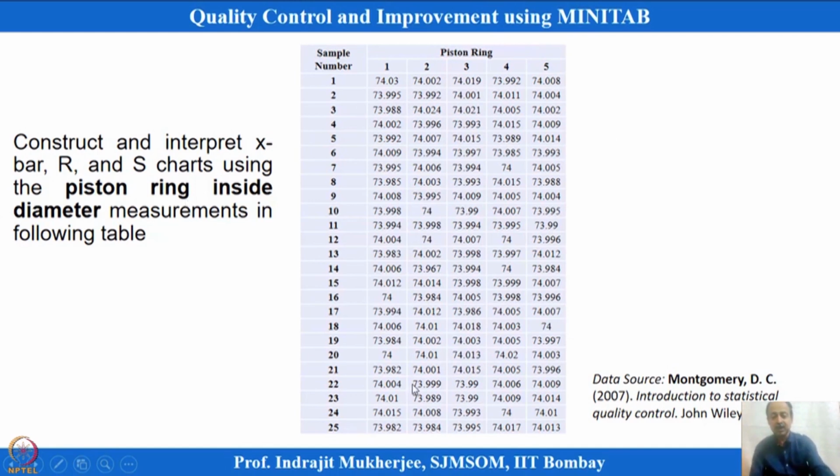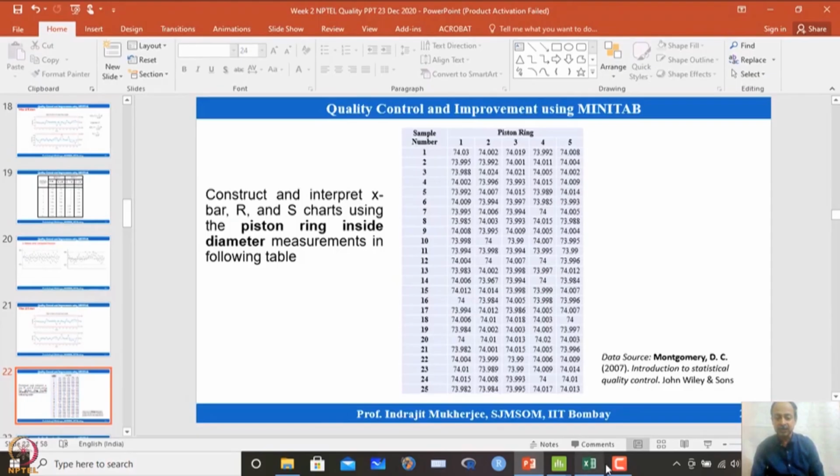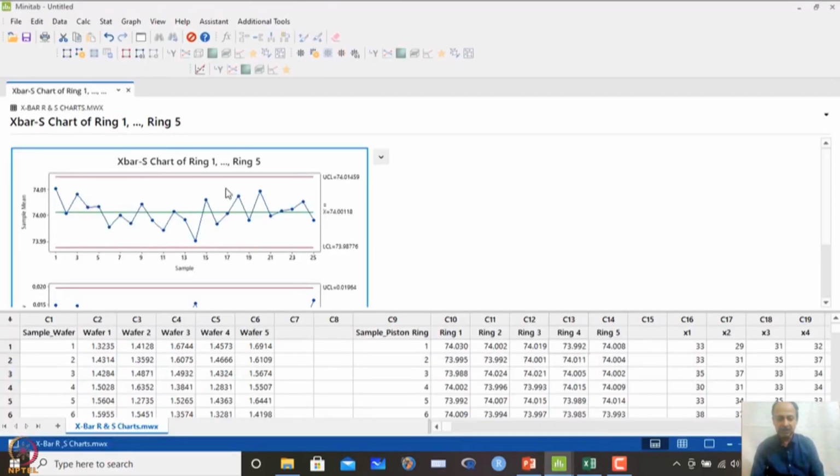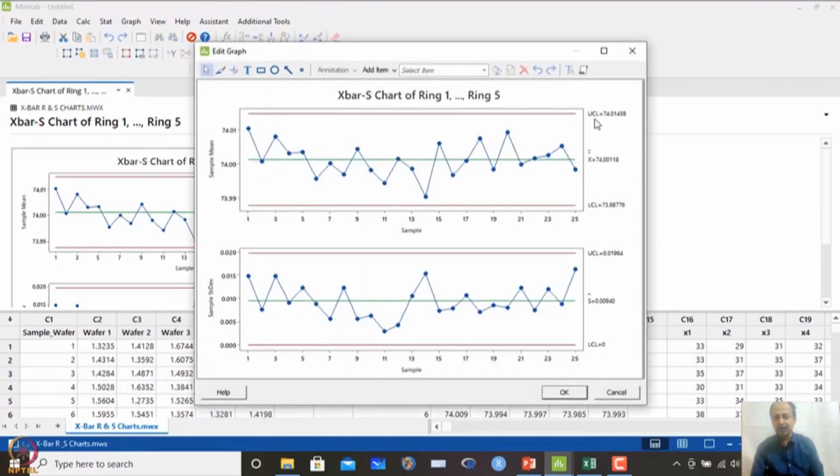Then what you will say to the operator is, let us use this control chart, and you will mention only the upper control limit line and lower control limit line, and maybe from T26 onwards use these limit lines to monitor the process again. Okay. Because this is natural variability that we are seeing, this variation can be used to express the natural limit lines, UCL and LCL.